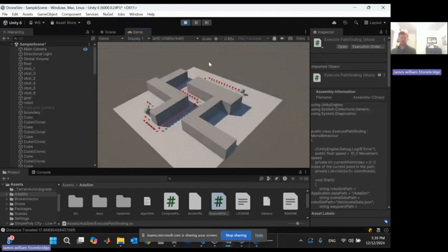All right, and as it runs, I'm going to point out a few things. First is that we've basically marked the path so that debugging is easier. I'm also going to point out that the robot has chosen a path that doesn't directly hug the wall, even though that'd be easier. And this is because of the object growth algorithm that we talk about in the paper.